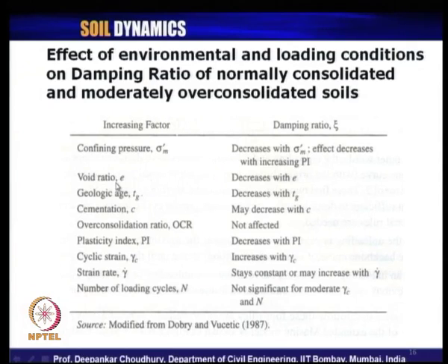Now, what is the effect of void ratio? If the void ratio increases, the damping ratio decreases. What is the effect of geologic age? If geologic age of the soil increases, damping ratio decreases. What is the effect of cementation? With increase in cementation in the soil, the damping ratio may decrease, but it is not so significant. The effect of cementation on the damping ratio is not very significant. The trend is a minor decrease in the value of the damping ratio with increase in cementation.